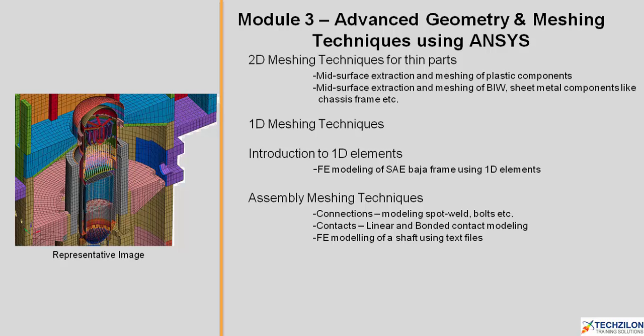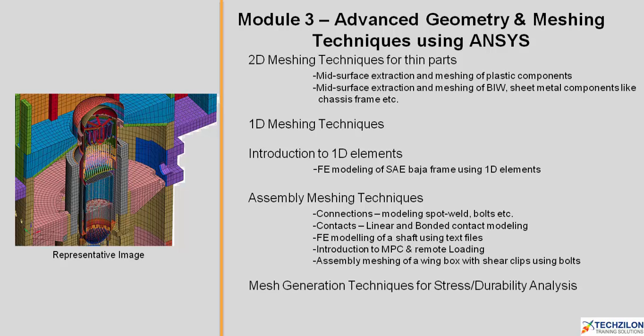You'll also be introduced to MPC and remote loading, assembly meshing of a wing box with shear clips using bolts, and finally you will learn mesh generation techniques for stress or durability analysis.